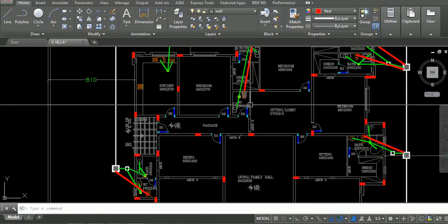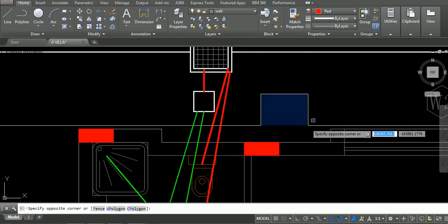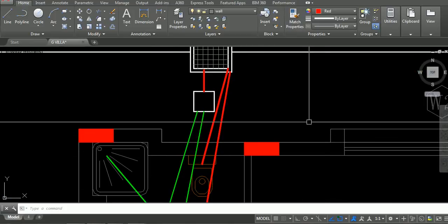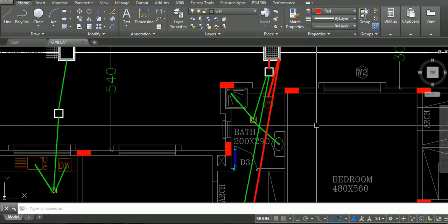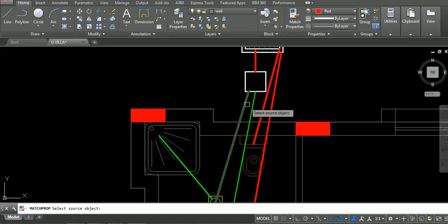So here all my sewage water is also connected directly to the manhole. There is no middle connection, which is the gully trap. The gully trap is only for sewer water. I will also explain later about it. But the main purpose for it and for the floor trap is for smell, so that smell will not come back to the bathroom. It's just like a shield, especially the floor trap.